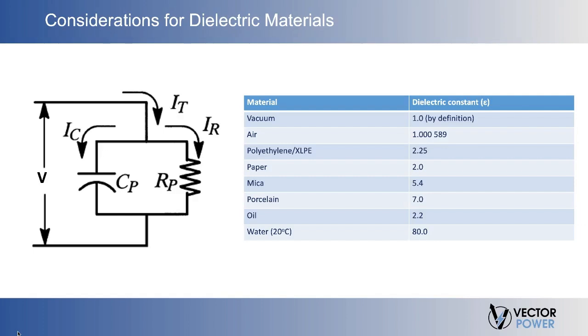Another consideration is the dielectric constant, which is the extent to which a substance concentrates the electrostatic lines of flux. Substances with a low dielectric constant include a perfect vacuum, dry air, and most pure dry gases, such as helium and nitrogen. Materials with moderate dielectric constants include ceramics, distilled water, paper, mica, polyethylene, and glass. Metal oxides in general have high dielectric constants.